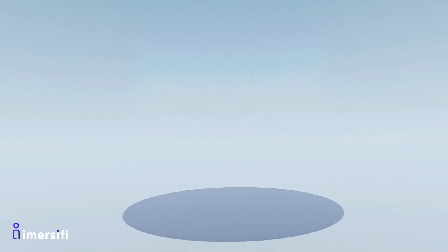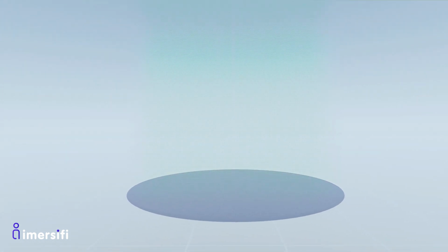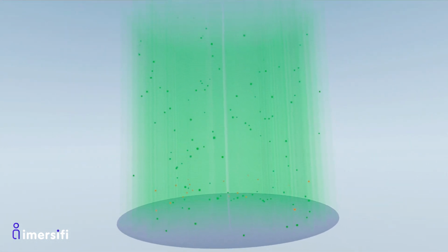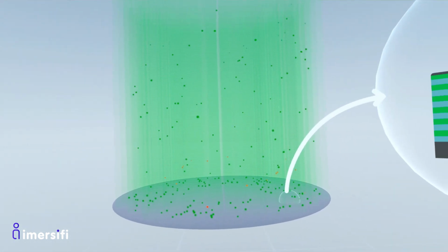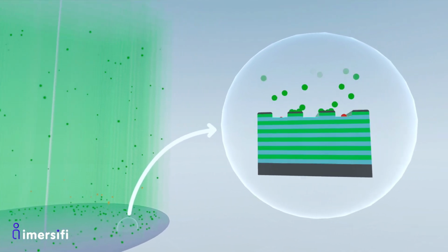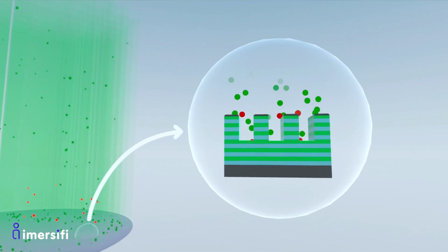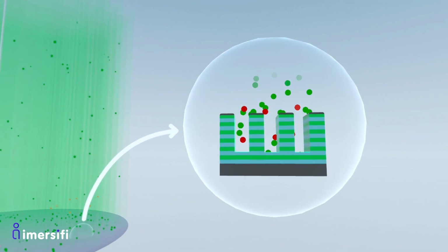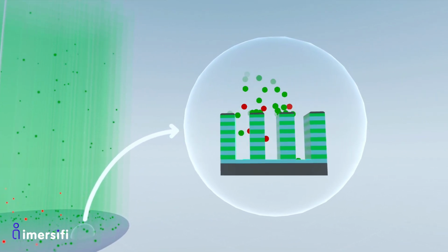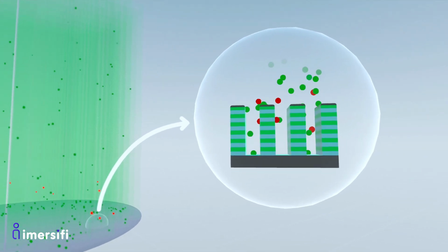Etching removes some of the exposed semiconductor material using either a chemical agent or a reactive gas called plasma. In modern semiconductor processes, plasma etching is replacing wet chemical etching. Plasma etching, also known as dry etching, is cleaner and more precise.